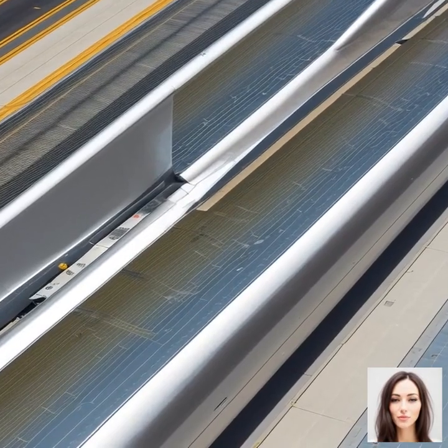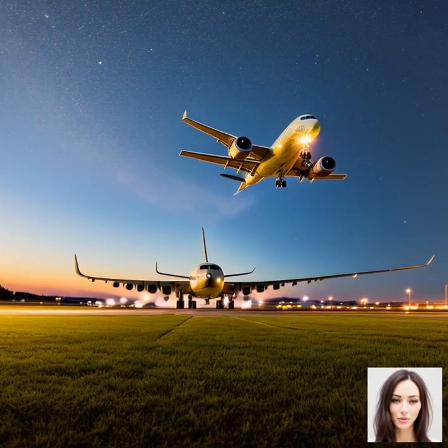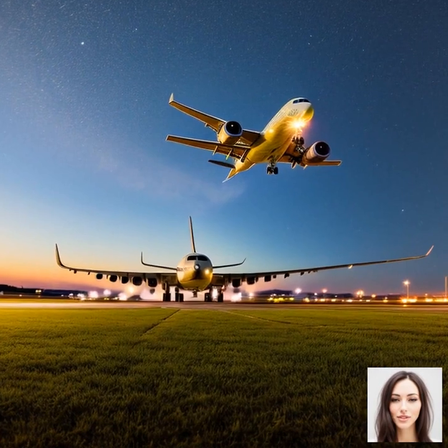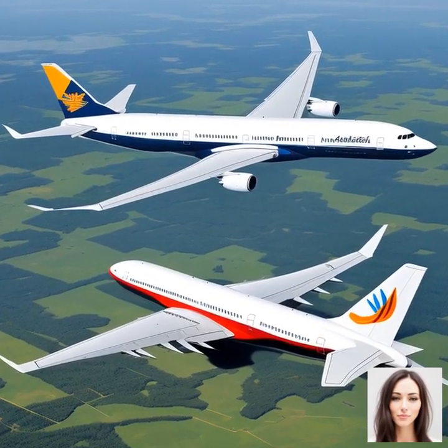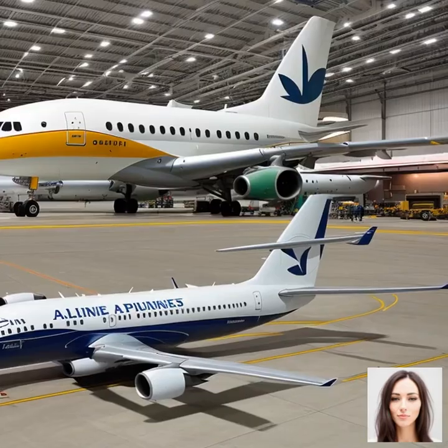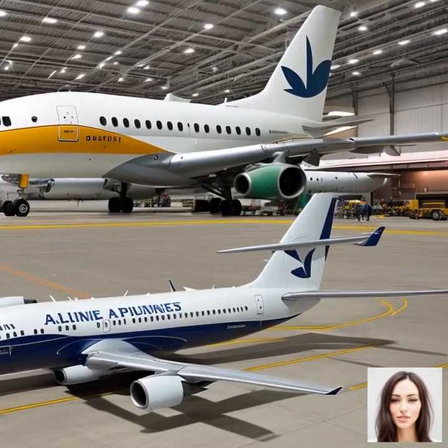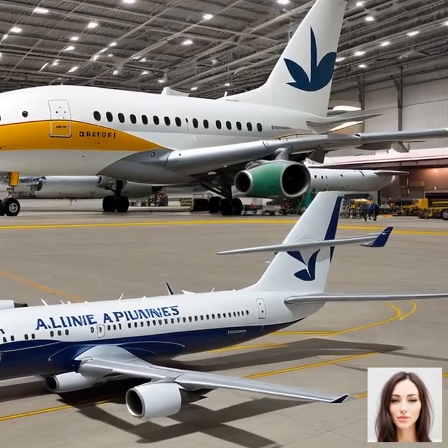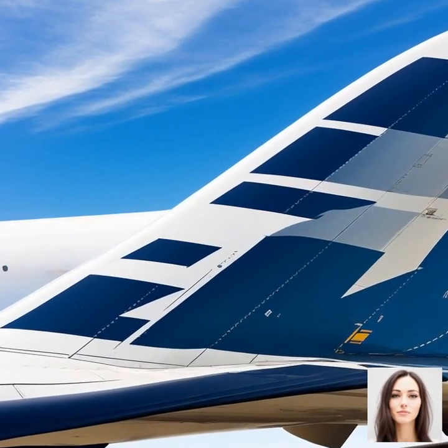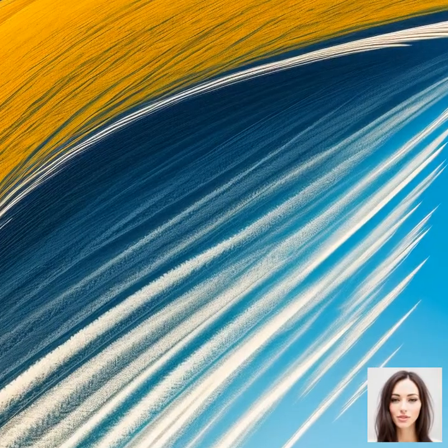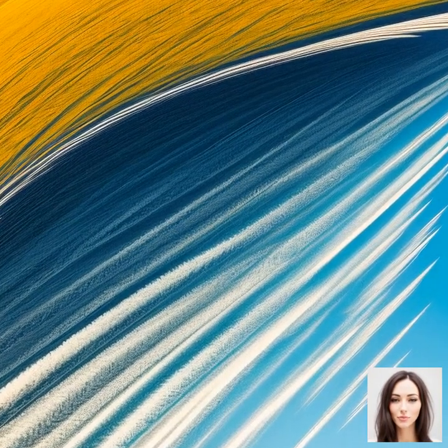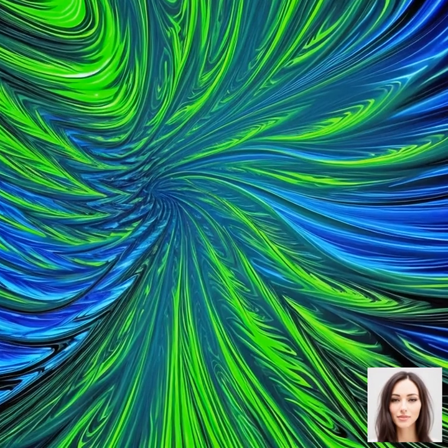It's important to note that the shape of the wing, specifically its airfoil design, plays a significant role in creating this pressure difference. So, Bernoulli's principle provides us with a fundamental understanding of how lift is generated by an airplane wing. By designing wings with the right curvature and airfoil shape, we can optimize the pressure difference between the upper and lower surfaces, maximizing lift and enabling airplanes to take to the skies.